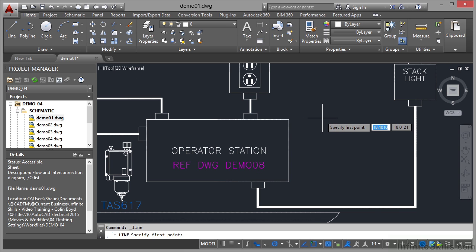Come into the drawing area. It's asking for the first point. So if I hover now over that corner, there's my endpoint object snap. Now what you'll notice when you've got object snaps switched on, AutoCAD will automatically auto-snap to these points. That's because auto-snap is a technology built into AutoCAD. It's a bit like a magnet and a nail. The nail will always go to the magnet, if you see what I mean. As soon as that endpoint snap appears, I click and I drag.